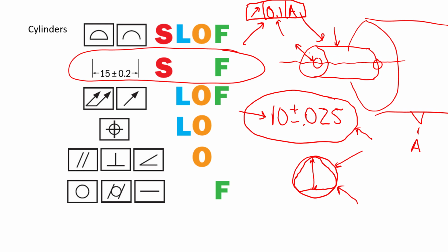So that means that our position tolerance would need to basically equal the remaining amount of that, because really what runout is, it's form plus location plus orientation error, all have to be built in within this 0.1. So it will still contribute to that runout measurement.